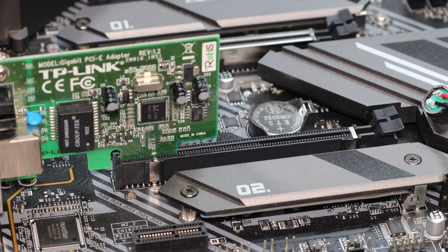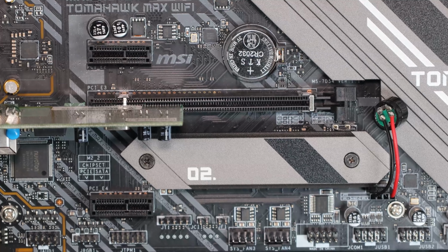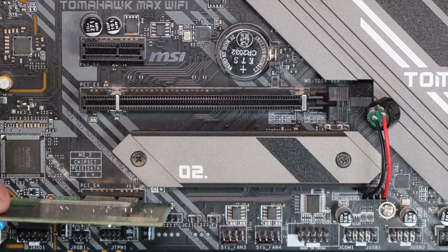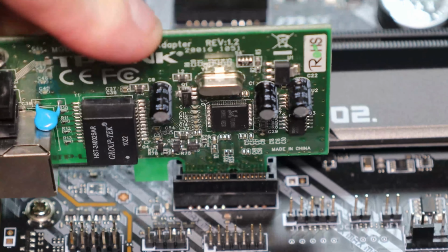When installing the network card, take care not to handle it by the sides, don't touch the electronics, and follow anti-static procedures. Since this motherboard has a by one slot, I will move the network card to this slot. This will mean there won't be any wasted lanes.